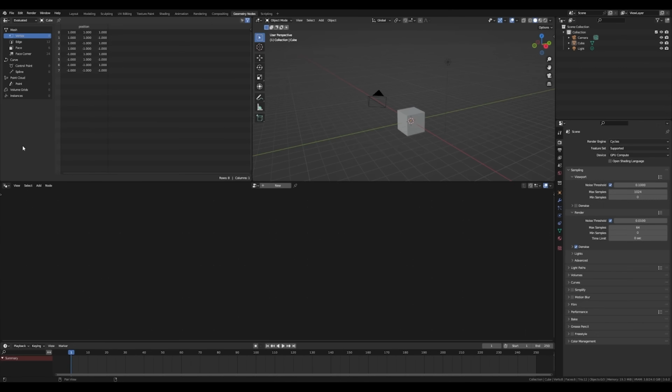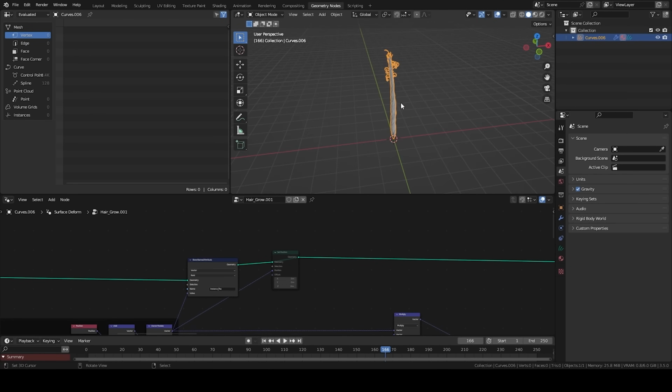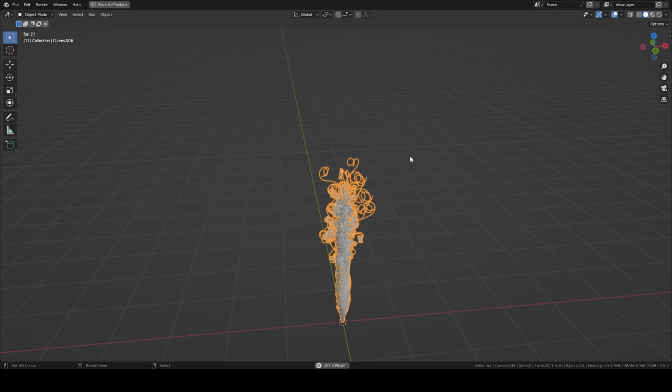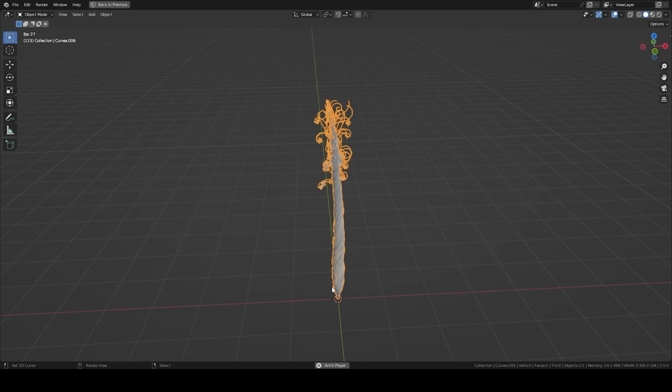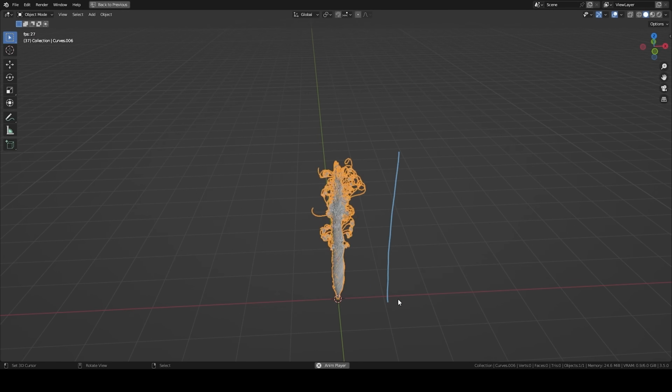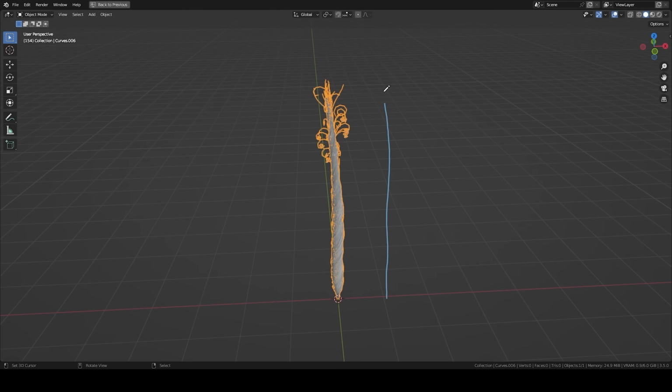So let's start. In this first part, we'll learn how to create this effect as an asset for future use in our shots. We will do it in steps. Create a vertical strand, duplicate it to have several around it, then duplicate them to form a cylinder. We'll have a distribution that will be rather homogeneous like this. Give them a little randomness also on the height so that we can go from about half of their height to their entire height in a completely random way.